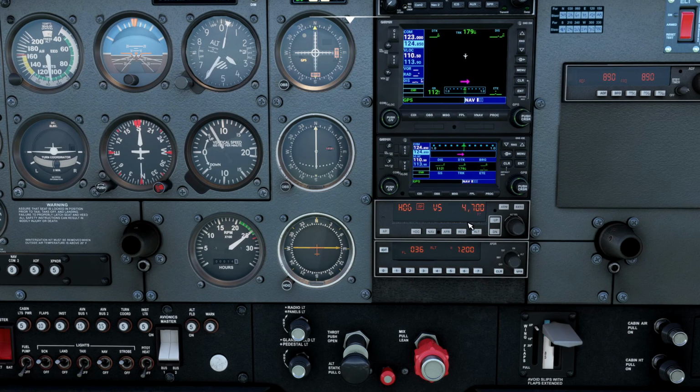There is an altitude alert function that is just below the altitude pre-select display. It comes on within 1,000 feet prior to your selected altitude. There it came on just there, and it extinguishes 200 feet from the selected altitude. It is a visual alert only. There's no audio tone associated with it. It's just a light that comes on the panel, basically.